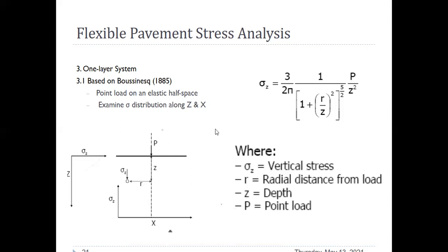It is the point load P over pi, times 1 divided by the ratio of the distance from the center, that is R, to the depth Z. So if the point is here, it is R distance from the center of the load, and you are interested in knowing the stress at this point at depth Z. The stress will also be calculated at this point, where the distance R will be 0.